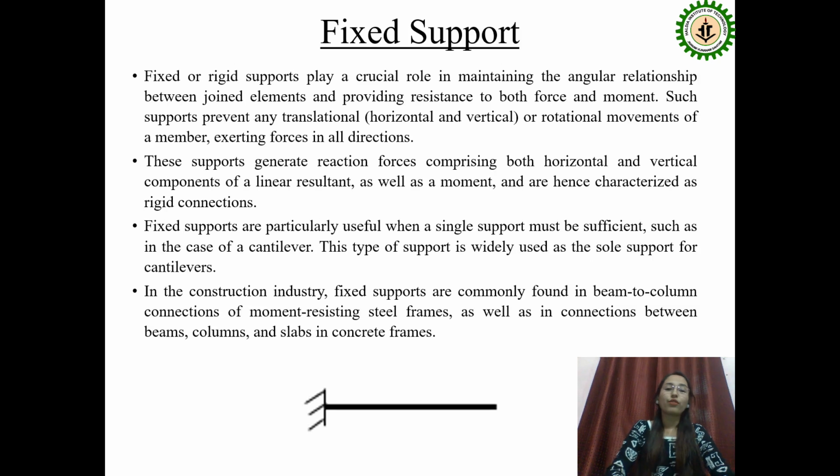Now for fixed support. For fixed support, the name already signifies the meaning of it, that the support is totally fixed. Neither horizontal nor vertical, neither rotational. No movement is allowed in fixed support. And we all know where there is restraint, there is reaction. That means for fixed support, horizontal side will have reaction, vertically it will have reaction, and for the restraining of the rotational, a moment will also be there in the fixed support. Therefore, fixed support has degree of freedom 0. That is, no movement is allowed. And degree of freedom is 0, but reaction is in all the three senses. That is horizontal, vertical, as well as rotational. That is moment.